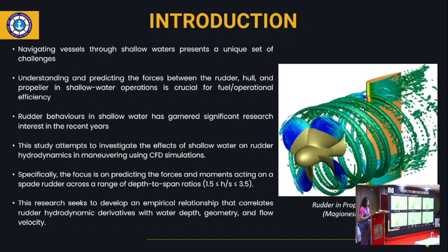So this is one typical case for 6 different depths. This gives the next different depths, and when we have h by s 3.28, we are more or less in a deep water case. So you see that very less interactions happen there. So there has been a drastic difference from what we started with, h by s 1.46, and what we have at h by s 3.28.